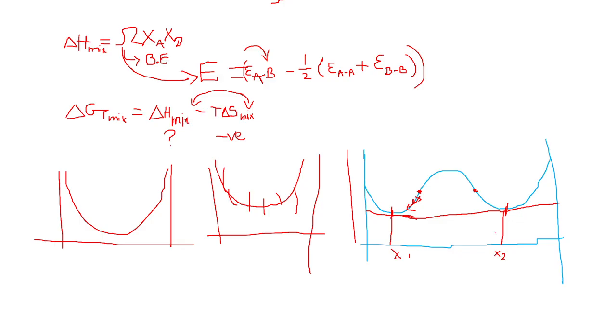So if we try to do higher undercooling rates, you will end up with bainite. And how the bainite will form: because of the low temperatures, the iron diffusion will become sluggish. And at one point, for lower bainite, even carbon diffusion will become sluggish, and they try to come out from the layer structure. Right, so that's why we form upper bainite and lower bainite, because of the diffusion of iron atoms and carbon atoms.